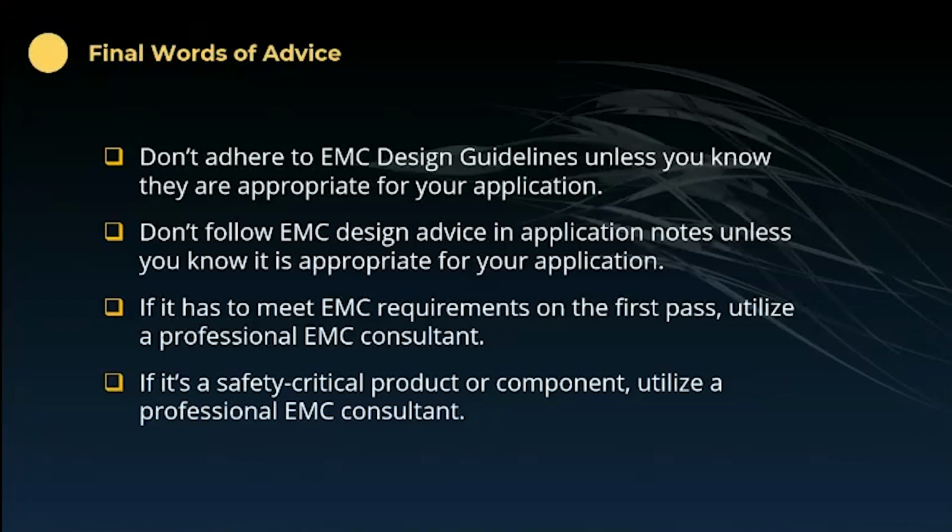And don't rely on application notes for your EMC advice. There's some really, really bad advice. They often will tell you to do exactly the opposite of what you really should be doing. Even app notes by very reputable manufacturers can have really, really bad advice in them.